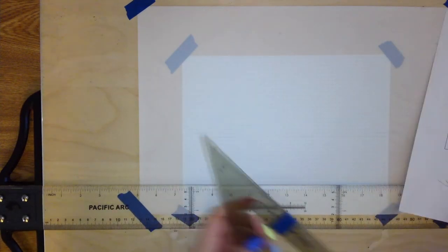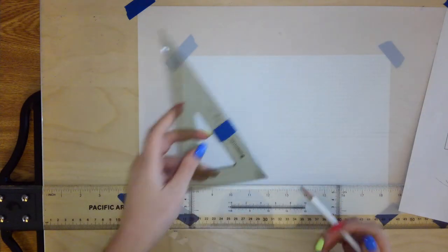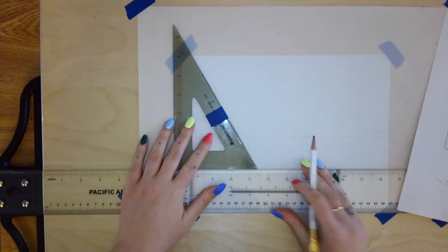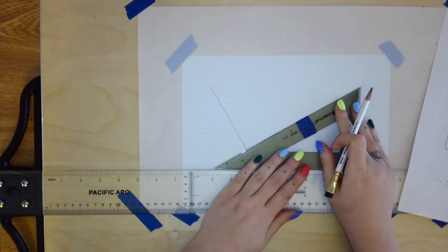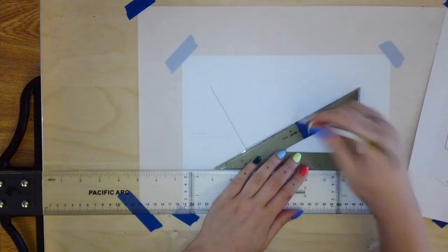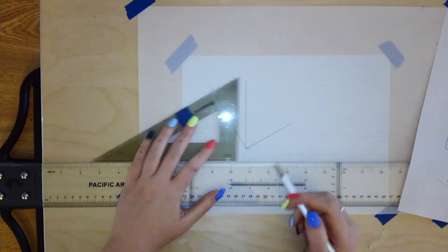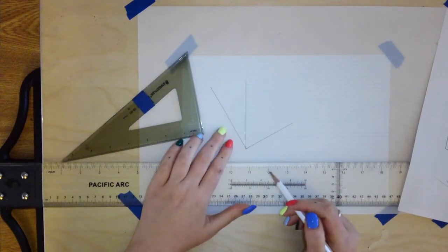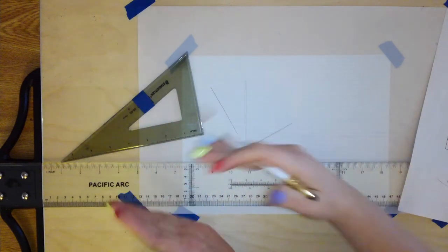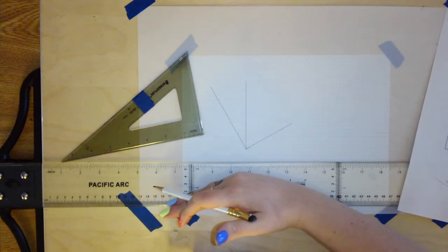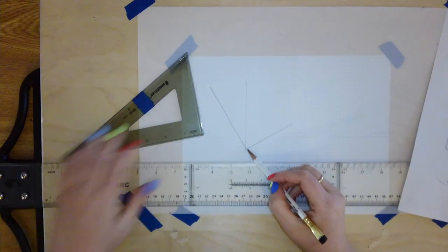So with a plan oblique, I am going to once again use my 30-60 triangle, but instead of giving equal emphasis, what I do for a plan oblique is I'm going to go 60 degrees in one direction, 30 degrees in the other one, and then directly up. So this still then is going to be my X, Y, and Z coordinate, but it's just kind of taking your orthographic that was laying flat this way and pushing it up to kind of give an emphasis to that height.